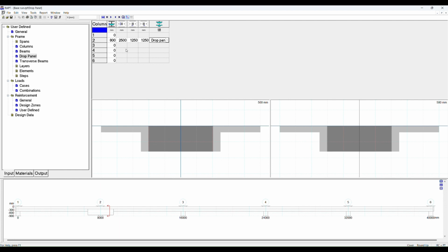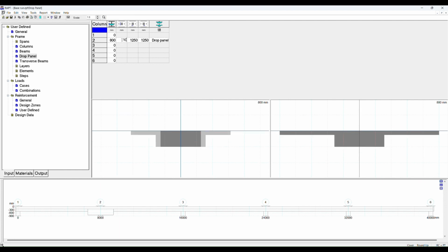And so let's make this smaller, and let's say this is a meter by 500 by 500. Then you can see that when the beam or the slab meets the drop capital, the step is too steep for that section to work flexurally. There is not enough distance for that shear lag to take effect.